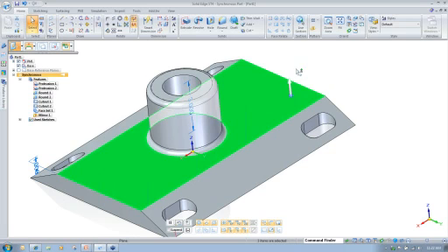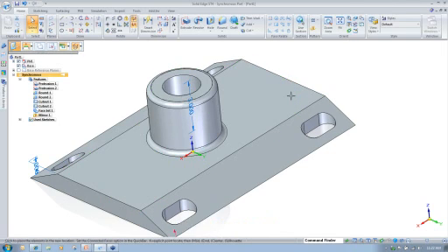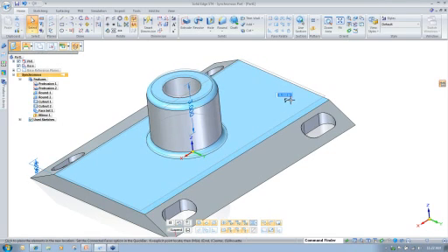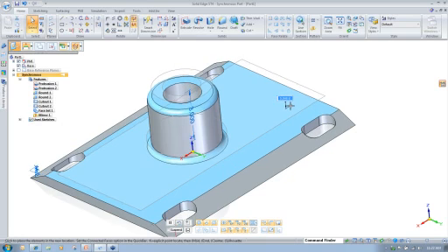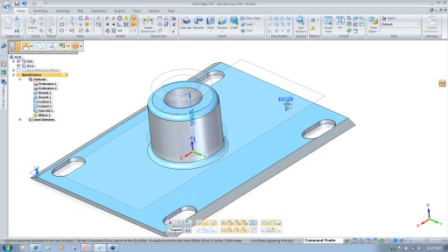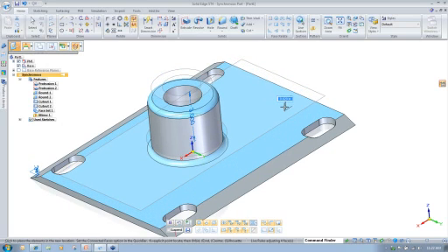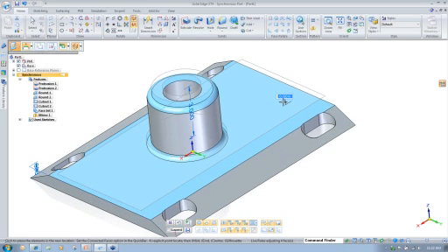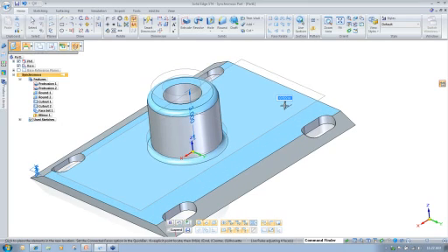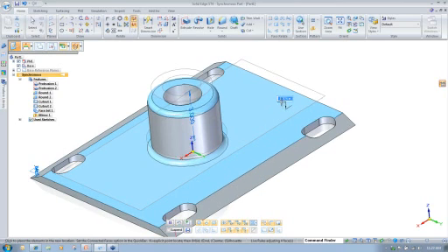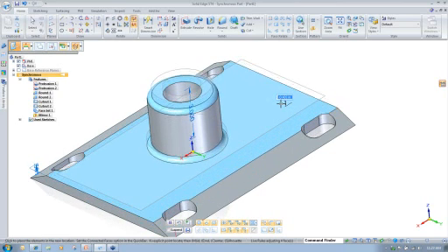So by selecting that and hitting the space bar, we can grab other surfaces that we want to maintain distances on. So I want to show you that that entire set of features are moving together just by simply grabbing the 2 faces that I want to maintain. You can see the 3-inch and lock that so that they move together and I maintain that 3-inch height.